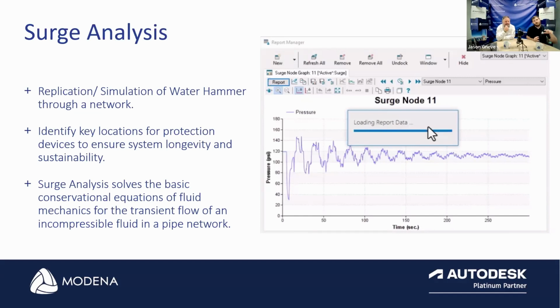Now from there, InfoWater Pro even allows us, even though we don't know the wave speed that may be propagating through this, to apply parameters and calculate what the wave speed should be for our given network. So even if we don't have live SCADA data that we are able to use to find those values, there is a calculation that we can run within InfoWater Pro.